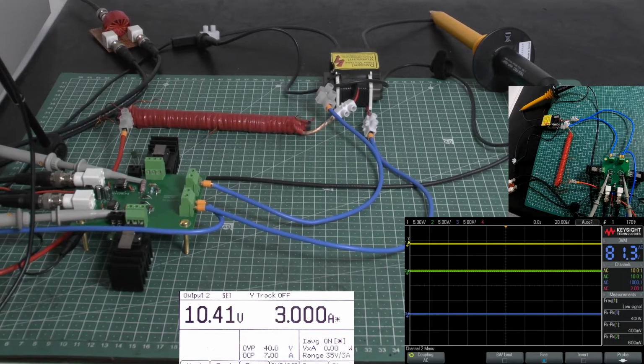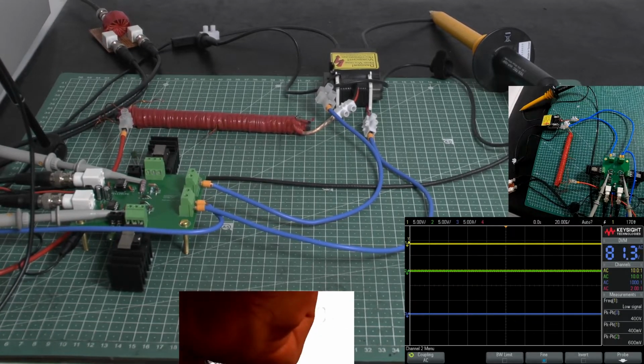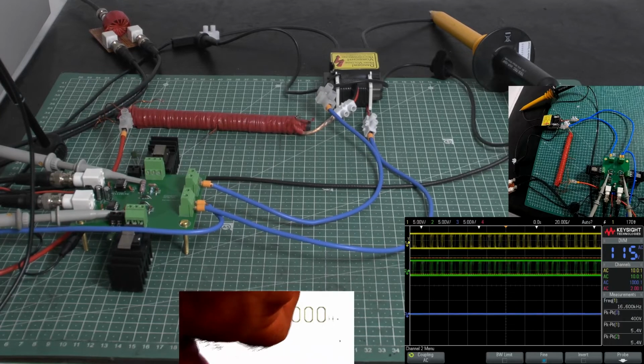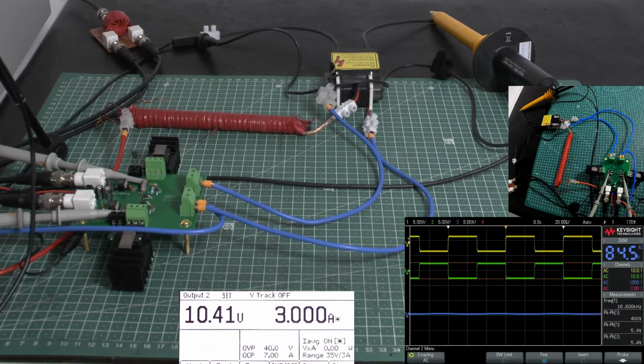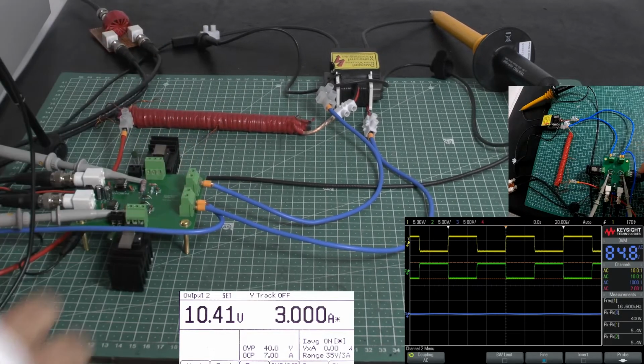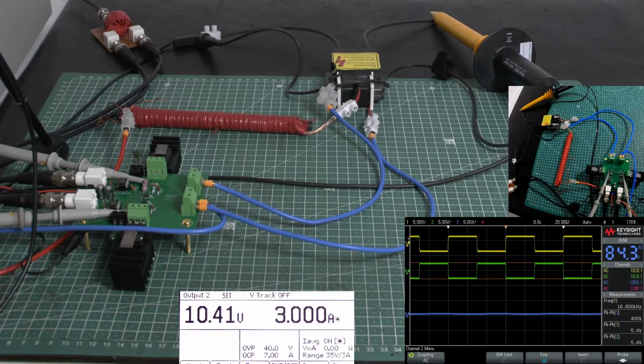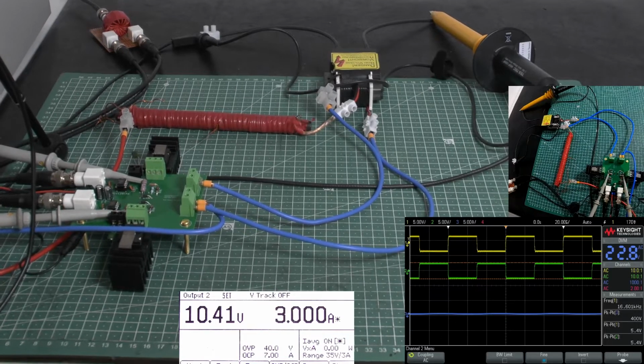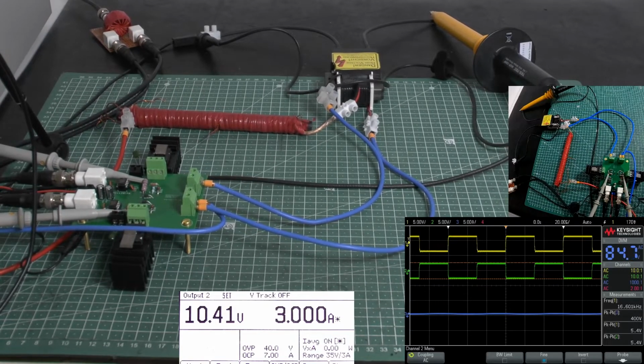So we're starting that one up. I have it at 6 volt. Let's do that at the moment. And the frequency is also a little bit lower. So we see what we can see now on our oscilloscope. We see the signal, and as you can see, the voltage level on both signals is identical. Absolutely clean signal is coming in via my signal splitter. The frequency is a little bit lower. Instead of 18 kilohertz, I have 16.6 kilohertz, as you can see.